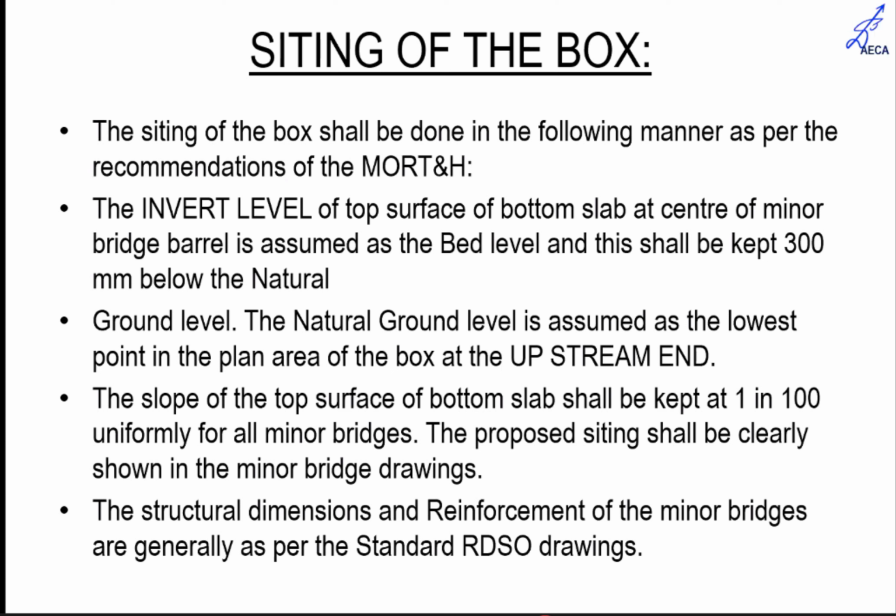The slope of the top surface of the bottom slab is generally kept at 1 in 100, uniformly for all minor bridges. Once the openings etc. are found to be adequate, then the structural dimensions and the reinforcements of these bridges are generally taken as per the standard RDSO drawings.